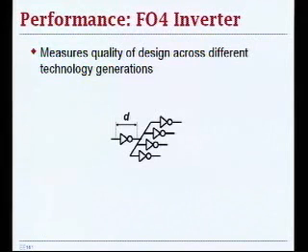For example, a 64-bit adder when designed for high speed is about 7 fan-out 4 inverters. So people can't really trick you when they say, oh, I have this design that's faster than yours, but yes, you have better technology, so how do you know? That's one of the ways you can really calibrate the delay performance of your circuit.